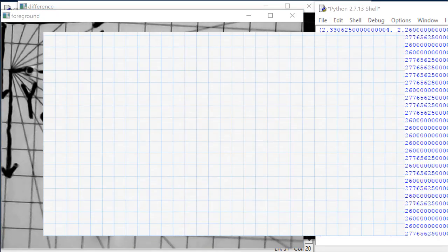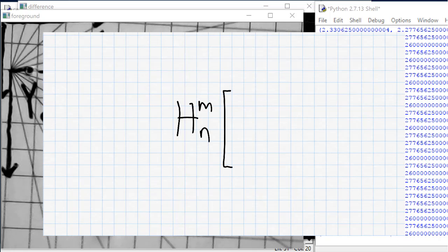Now, there's an interesting function from way back in our kinematics study that we can use now to solve our problem. Suppose you have a homogeneous transformation matrix from one coordinate frame, M, to another, N. And suppose you know an XYZ point in frame N, and you want to know the location of that exact same point, but expressed in frame M instead.